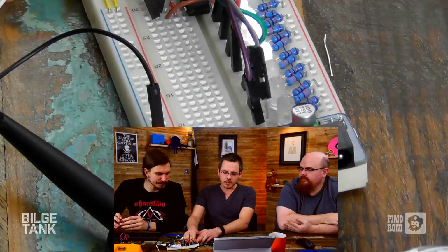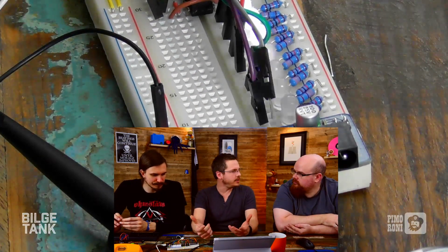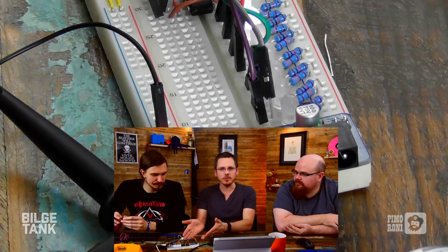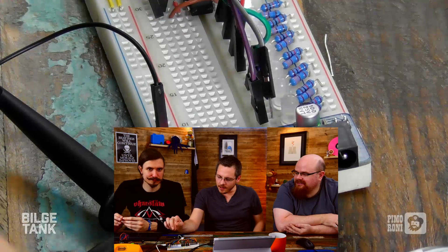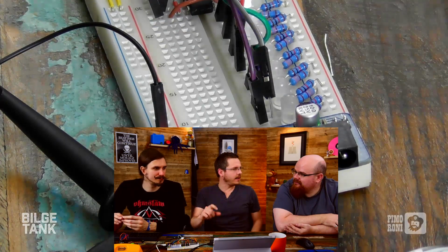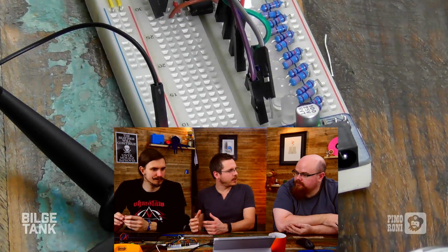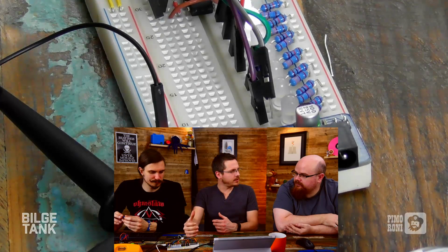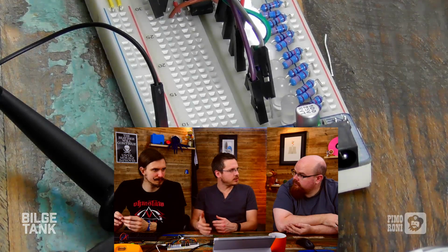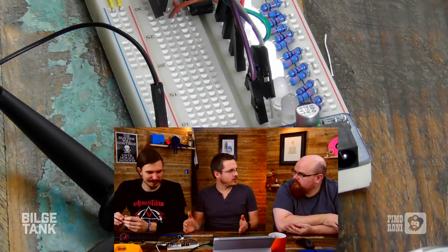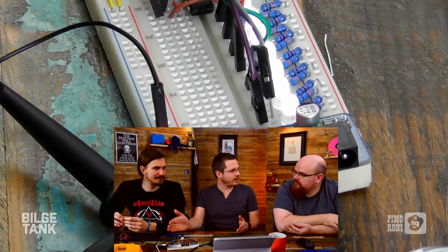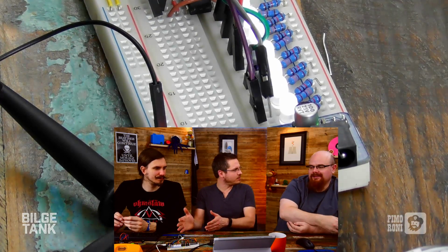Right. The main downside with these is that normally you would always buy an ADC in a chip, because why on earth would you do all that when you can just stick a little chip on? But obviously for this, for every discrete value we've had to add a whole separate comparator circuit. Yep. So you can imagine a 16-bit ADC that has 0 to 65,535 as its value range, you basically need to scale this out that many times. Really? Yeah, you need 65,000 times as much of this to represent that, basically.